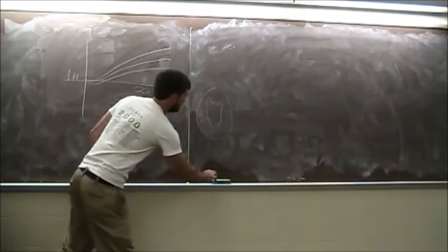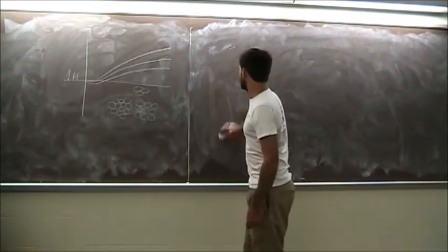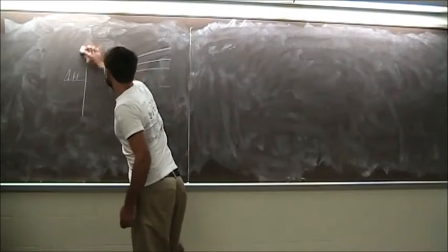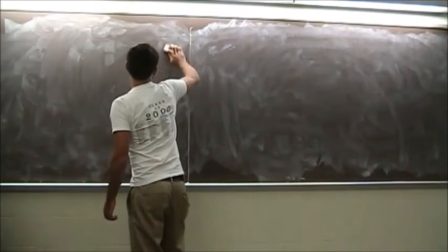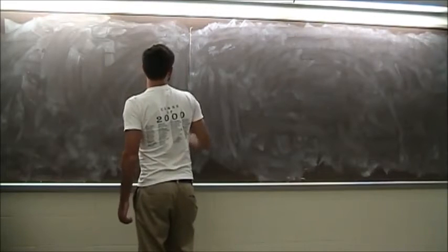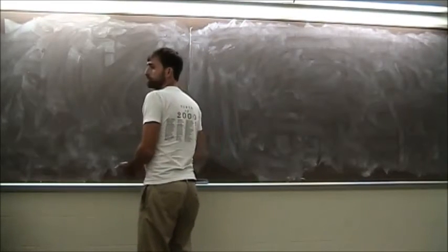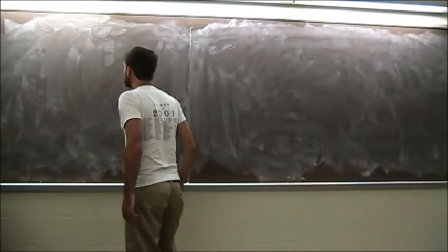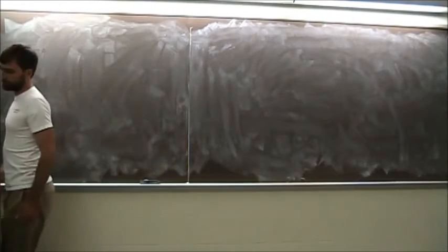There's one more key thing I want to talk about with this direct shear test. One of the major disadvantages of running this test is that during the test, we talked about principal planes earlier, but during this test, the principal planes are allowed to rotate.